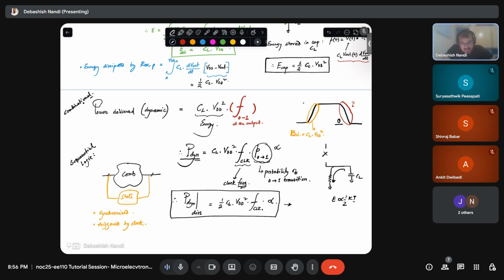So it is directly proportional to your temperature. So your temperature is increasing. What will happen if your temperature increases? Your mobility will decrease, your threshold voltage will take a toll, right? All the semiconductor parameters we calculate at one particular temperature. If we change the temperature, everything will change, right?